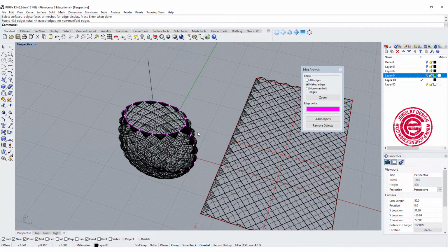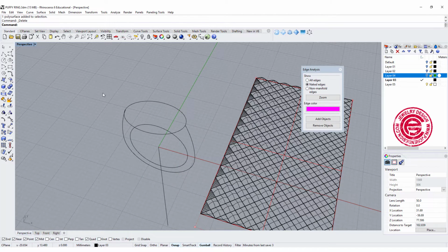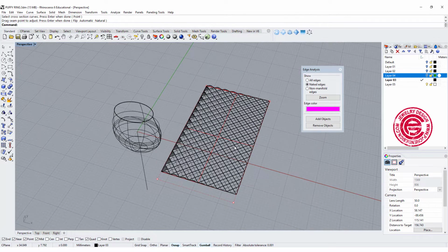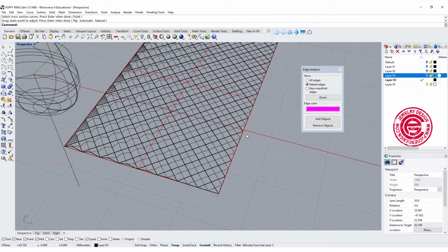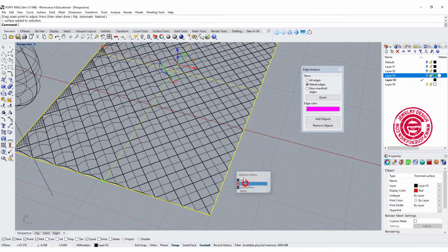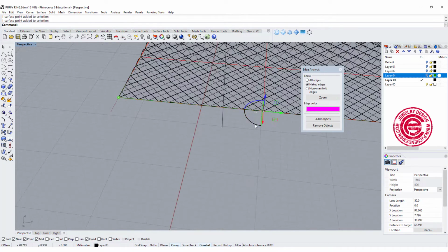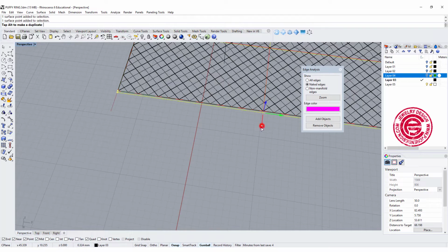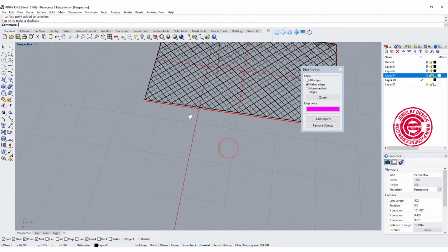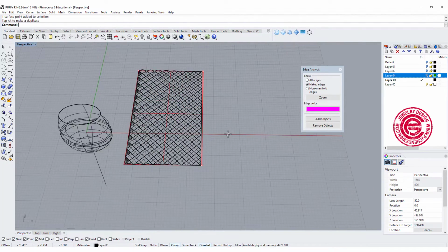A few things, I would like to share my little trick with you. We're going to delete this one. We're gonna do one more time. First of all, to avoid all the points coming into one point on the bottom, like what we see there, that usually causes some issue. So what I like to do is I'm going to pick up those 2 points and just move them out a little bit. So that way when we flow it back, there will be a hole on the bottom. It won't be coming into 1 point. So that way will help a little bit.